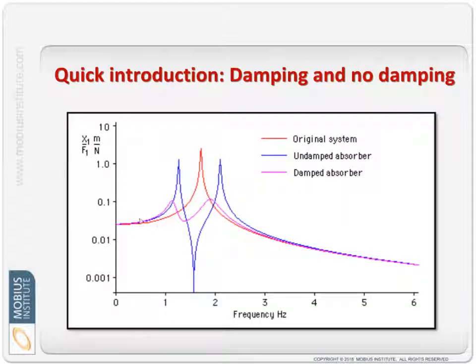In this case, you see, this was the original system with the natural frequency. If all we do is add the spring and the mass to create a single degree of freedom sort of resonance, what we do is we completely split it. So we end up with sort of an in-phase mode and an out-of-phase mode, and there's a lot of attenuation right at that frequency.